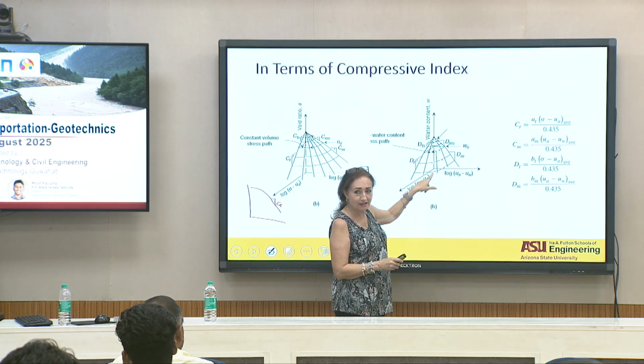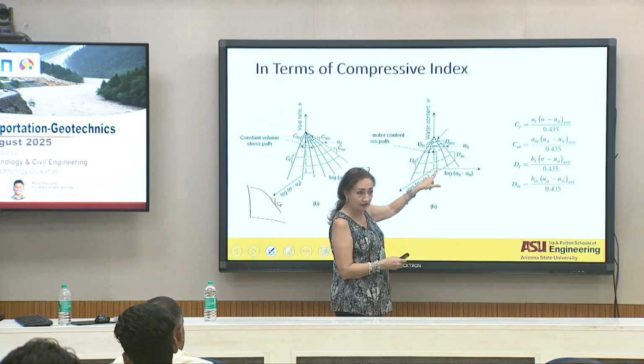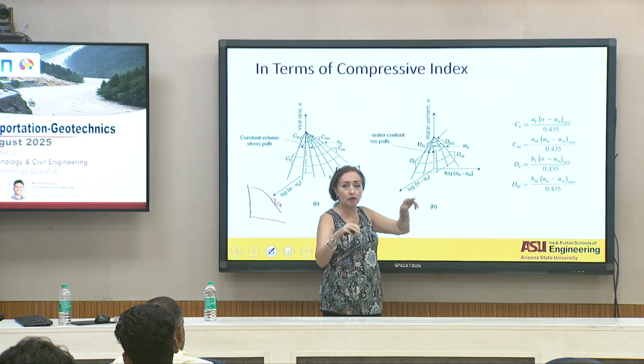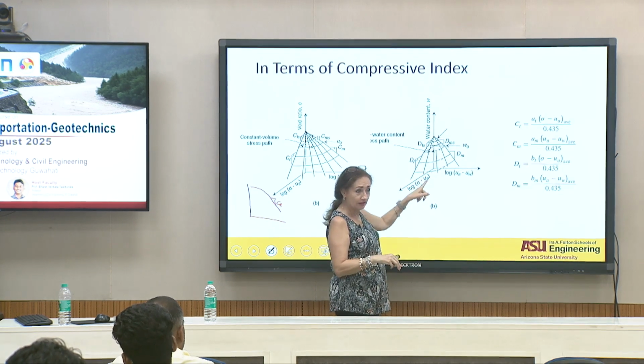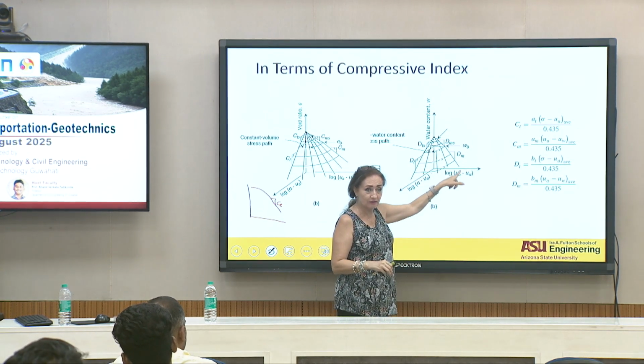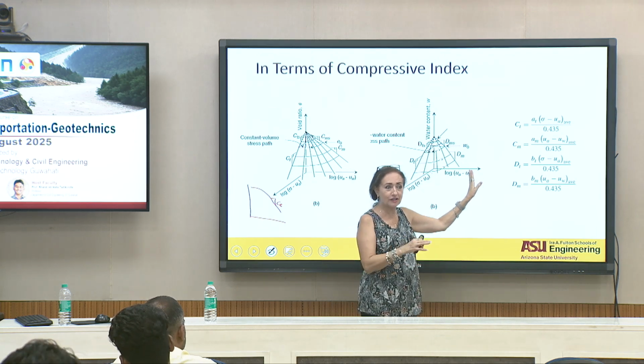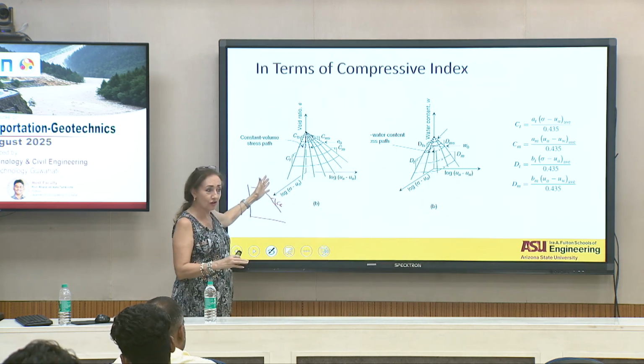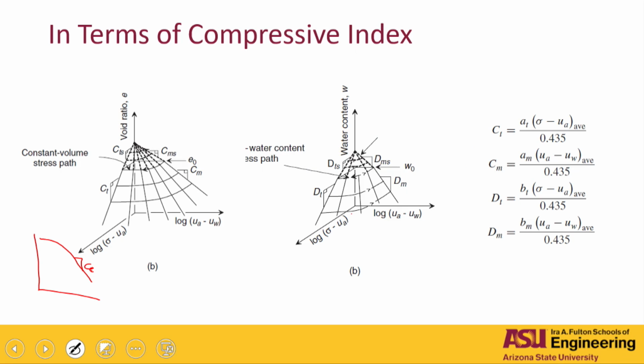That's your soil-water characteristic curve, right? That's the extreme one. If you just do a soil-water characteristic curve with no external load applied to it, that's your soil-water characteristic curve. So this is the curve that you have learned these four days, and this is the curve you learned during your consolidation analysis, right? In that way, you do have all the compressibility due to a combination of the effective stresses, and you can represent that in a constitutive surface.